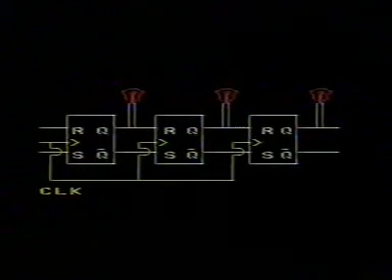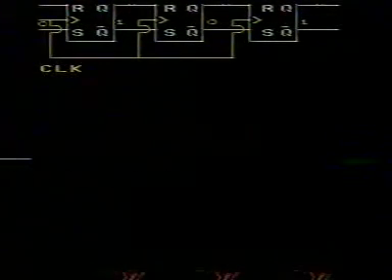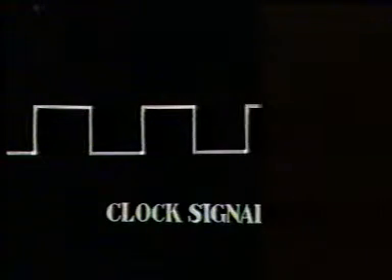So to regulate this, the clock signal is used. This synchronizes the working of the flip-flop just as the policeman was regulating the flow of traffic. Now, as the input data arrives, the clock signal causes the outputs to change uniformly and only at certain specified instants of time. This is much more ordered and the whole system can work synchronously. A square wave is generally used as the clock wave or the triggering input.